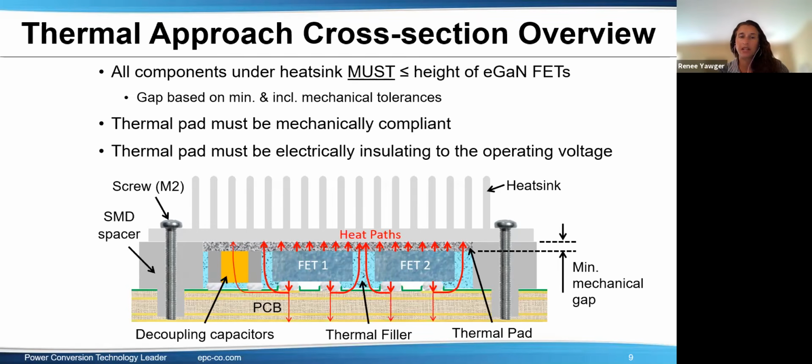Can high transient current spikes cause thermal shock to the FETs or create local hotspots within the die, say a couple of 100 amps for microseconds? Yeah, there's thermal transients, and that's detailed in our data sheet. There's curves in the data sheets near the back, typically like the second or third page from the back, that shows the thermal transient response of the GaN FETs with pulses.